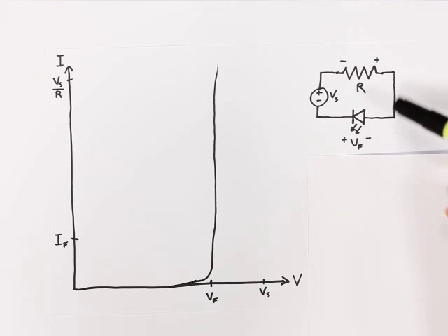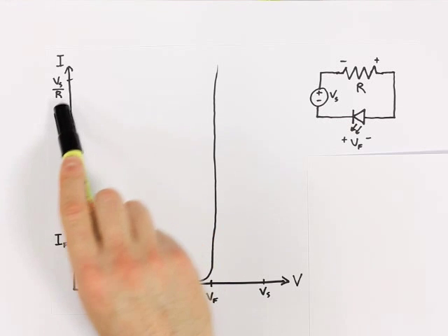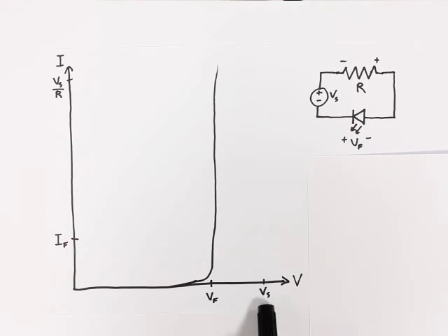Now we'll solve this circuit to get a value for our resistor. I'm going to start by using the graphical method as described in lecture S6V6 of 6002X, but I'll skip through a lot of the math. So all we need to do in order to calculate where our circuit will be operating in terms of voltage and current is draw a load line across our VI characteristic for the LED. So we just draw a line from current equals Vs on R, up here, to voltage equals Vs. And the intersection point is what the operating current and voltage of our LED would be.